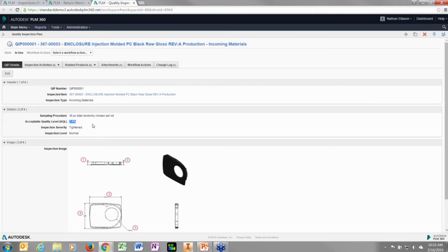In this case, the 2.8% dictates that if we have 1 or 0 parts that fail, then we can accept the full lot. If we have 2 or more that fail, then we have to reject that lot, and we have to determine later what we want to do with that. And I'll talk about that in a few minutes.